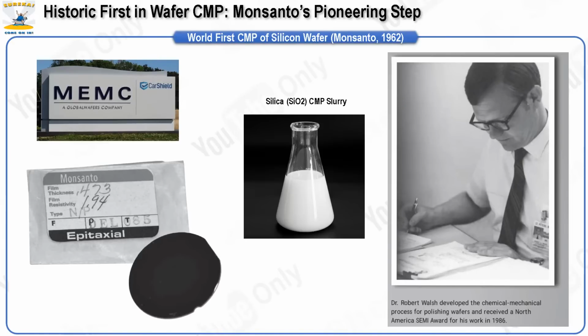However, upon closer investigation, he discovered that the improvement was actually due to the gradual incorporation of silicon into the polishing slurry. As the wafers were polished, silicon material from the wafers was being abraded and mixed into the alumina slurry. This unintended addition of silicon particles effectively created a self-regulating mixture, where the abrasive action was modulated by the presence of silicon particles in the slurry.